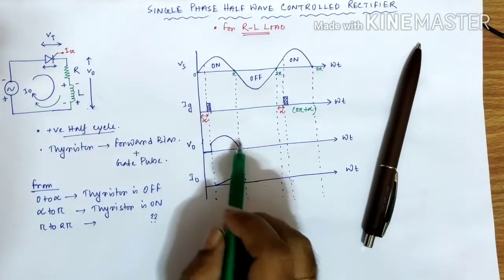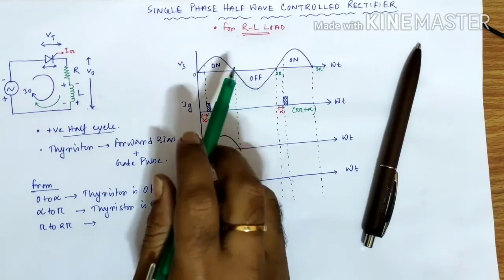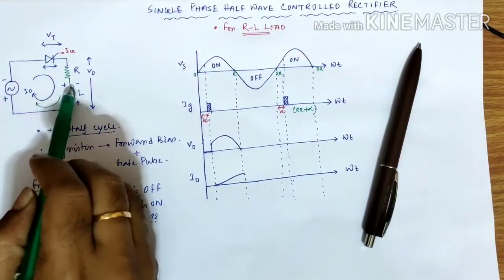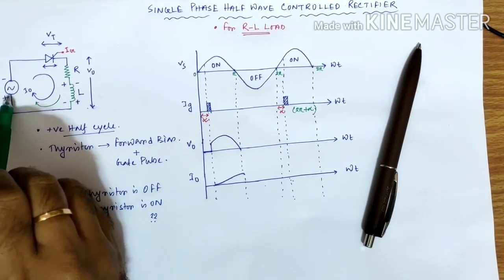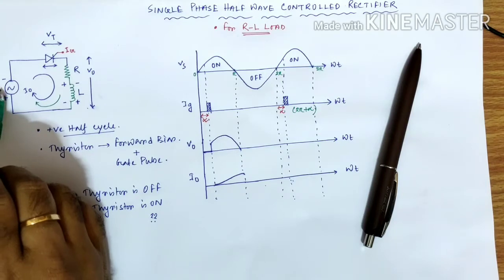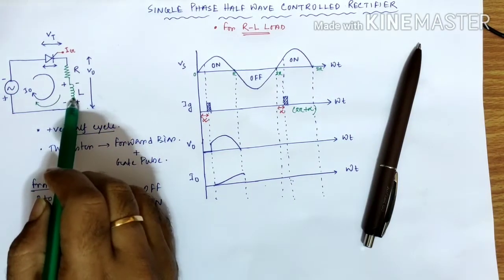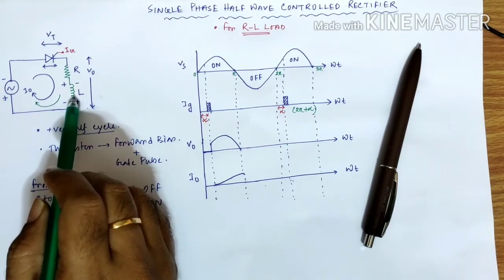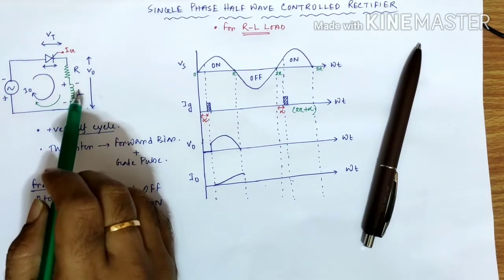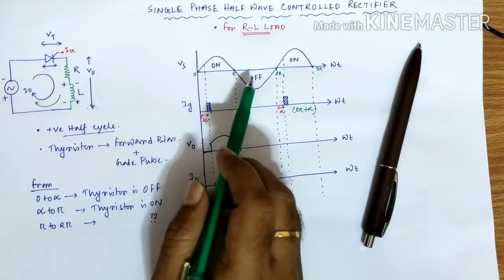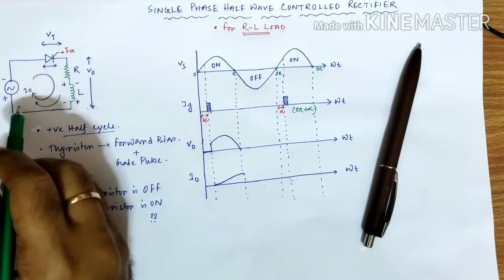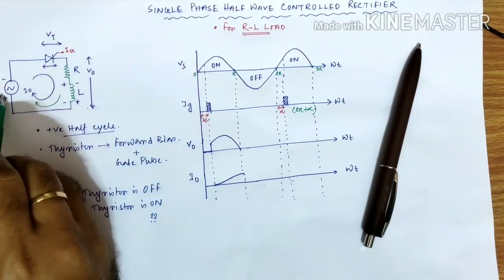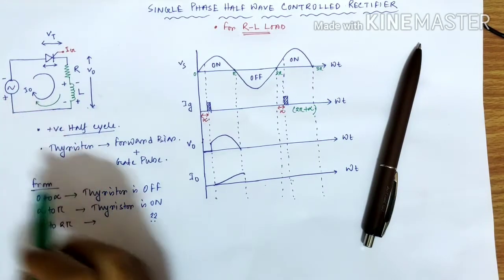So at the beginning of this negative half cycle, the circuit has two energy sources, both with polarity like this one, minus plus, but this voltage source has an amplitude which is very much less than the inductor, which has already attained its maximum value. So at the beginning of this negative half cycle, this inductor becomes the dominant source over this voltage source.